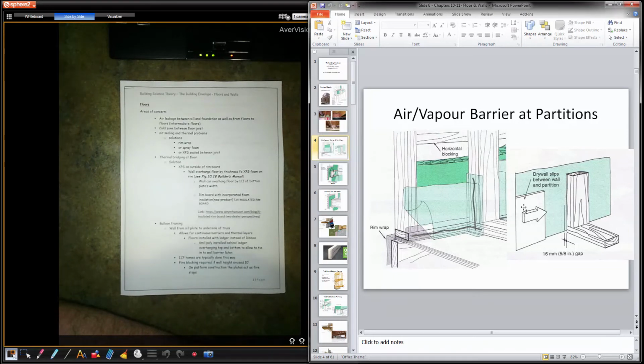In this case, they're also putting the drywall through, which then creates a really good fire stop, as opposed to having the drywall come in, stop, drywall come in and stop. So if the wood here were to burn, the fire can go through where that stud was. If you have drywall behind that stud, then it has to burn through drywall to get to the next room. Not a lot of people are doing that, but it's definitely a good practice. It's a little extra time, harder to put the drywall through, so that's why people tend not to do it.